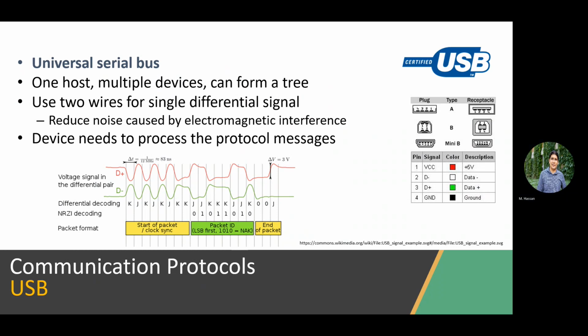Why am I doing this? Because simply sending the same bit of data over two wires allows you to restore, even if there is a distortion, you can easily avoid the noise there, because the noise does not affect the wires similarly. So even in the existence of very high speed and very high noise, I can restore my original signal at the receiver side. Good. This is what we mean by differential signals. Two wires used for the same one bit of information in a negated way. Good. If you look into any data sheet, you'll find clock and clock bar, for example, right? Bar is the negated part of the clock, and this is a differential clock.